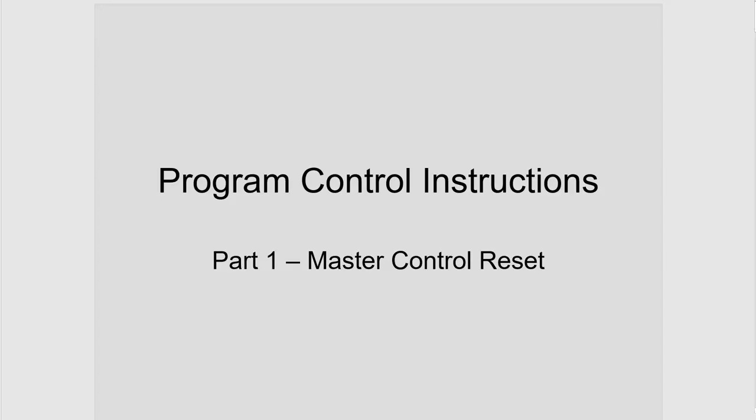Program control instructions are used to alter the program scan from its normal sequence. Now, this can shorten the time that it takes the program to scan. Program control instructions optimize the total system response by executing certain routines only when required in the program. It's mentioned here.